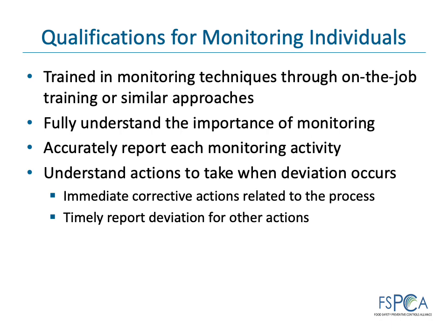For example, a line worker on a final packaging line may be trained in monitoring activities at a metal detector. The individual can investigate detector rejections, kickouts, to determine cause, document findings, run calibration checks, etc. without direct involvement from supervisors. This person could even shut the line down if issues are identified and then inform supervisors for more in-depth investigations.